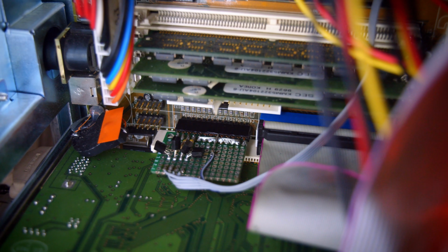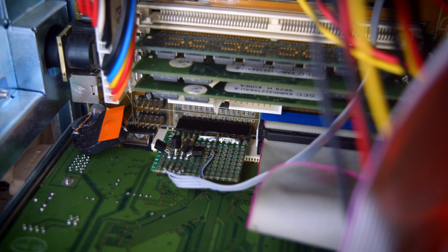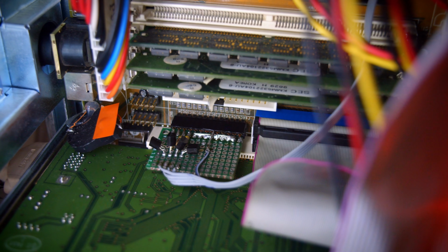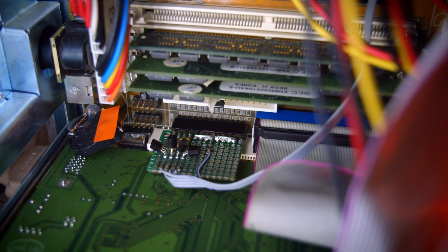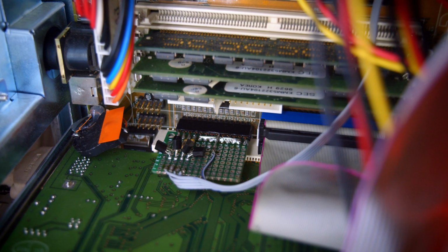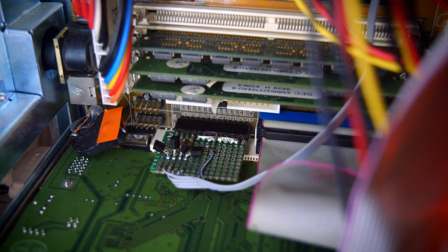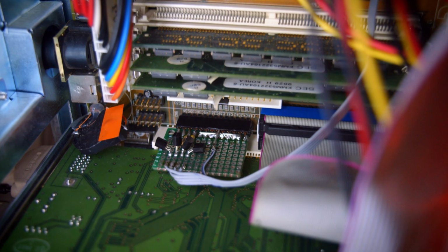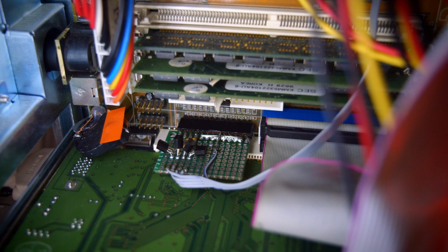Now, the actual XA1541 adapter is really simple. You can DIY one of these without much effort at all. You just need 4 NPN switching transistors and 4 4.7k ohm resistors. And that's it. Then you just need to figure out how you want to connect it to your computer.